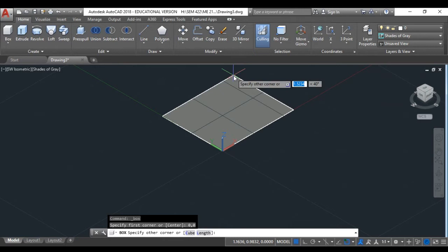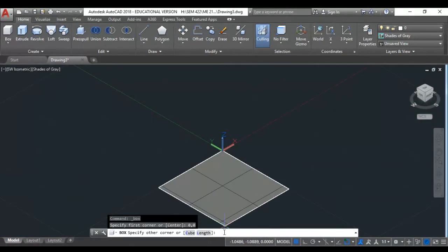See, guys, whatever I wrote down here, actually it should be in this box, but I need to eliminate that box. Remember, sometimes this box gives us trouble. How can I eliminate the dynamic input? Somebody remind me, we did this a lot in the 2-dimensional. This is the dynamic input, F12. Yes, sir, thank you so much. F12, and now you are free to go and locate the opposite corner.